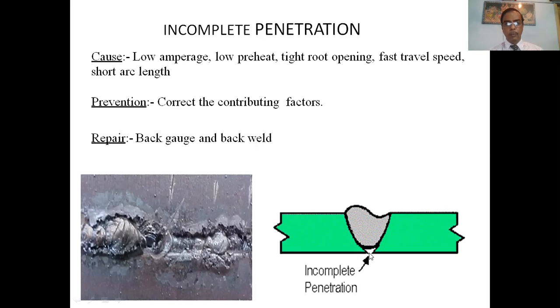Incomplete. This is an incomplete root. So there is a gap in the root, so penetration is not properly done.